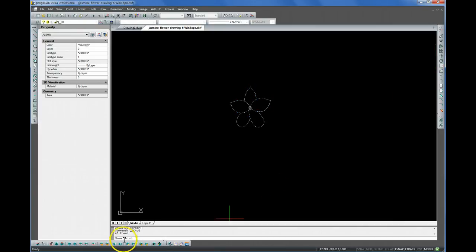It's asking for a base point. That means the zoom point, if you will. Middle is fine. Actually, a better choice for the base point would be this, because there's another thing we're going to do before we send it in. This is the origin, and we'd like this drawing to be centered about the origin or close to it. It will make the import go better. So click the origin and that'll pull it there.